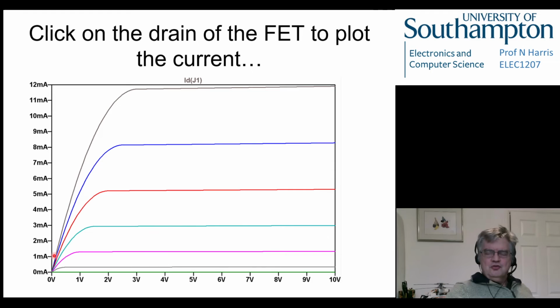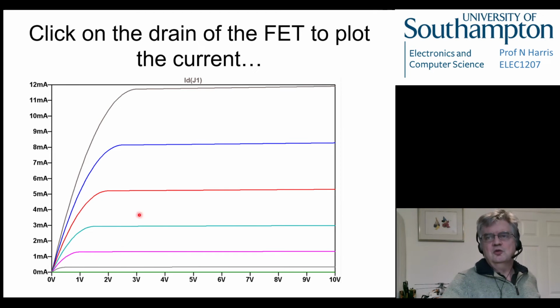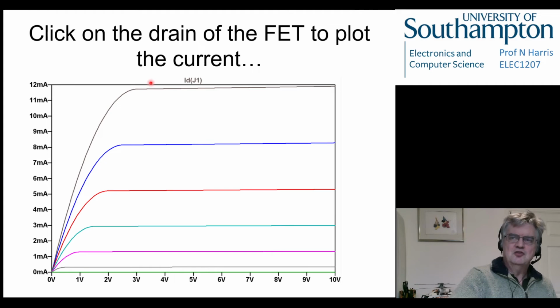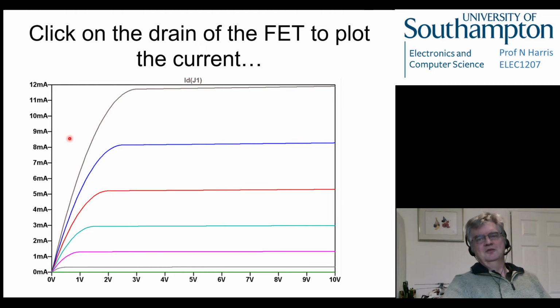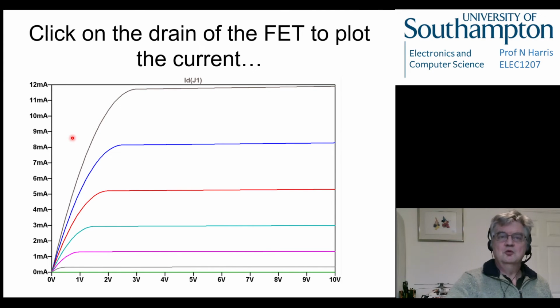So this allows us to create effectively the transfer characteristic of the FET within SPICE for any device we like, and then we can get into the model of SPICE and tweak its various parameters and see what effect it has. So you can see it's quite a powerful thing. And look, we were expecting 10 milliamps, but it's actually told us we're going to get about 11.8 or something. So there's obviously some variation in the model, but that's okay because we're allowed to have anywhere between 2 and 20 really. So you might be better off assuming that you get 12 out of it really.